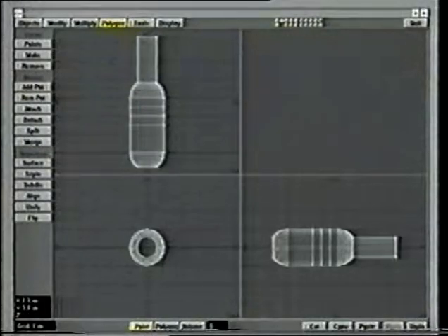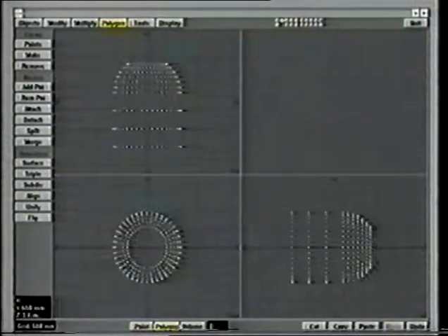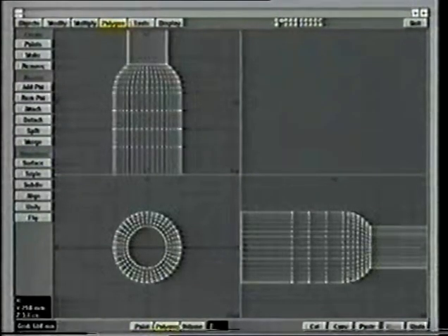And my general philosophy tends to be to make simple shapes and then just expand upon them and keep everything separate until the last minute when you assemble it all, and then take it into layout and start your rendering and surfacing. So, I just want to remove a couple of unwanted polygons from this, being as both ends of this cylinder here are still there and we don't need them.